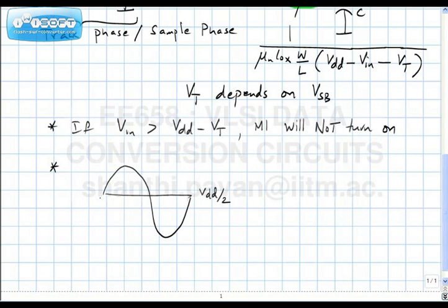If the bandwidth is sufficiently high, the output should follow the input as long as the switch is turned on. But now what is happening when the input goes high? What happens to the bandwidth of the RC network? Reduces. So if the bandwidth of the network reduces, what can you conclude?